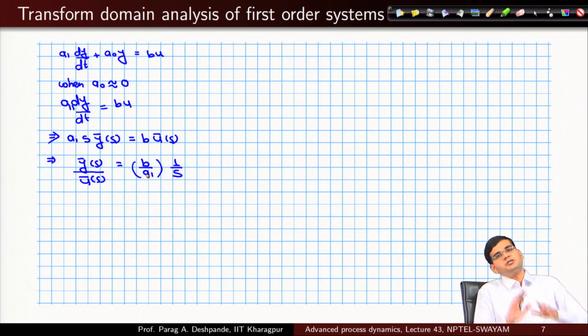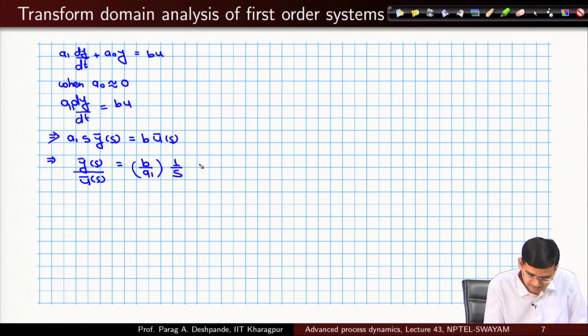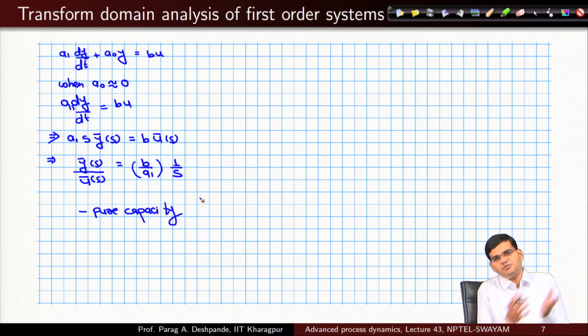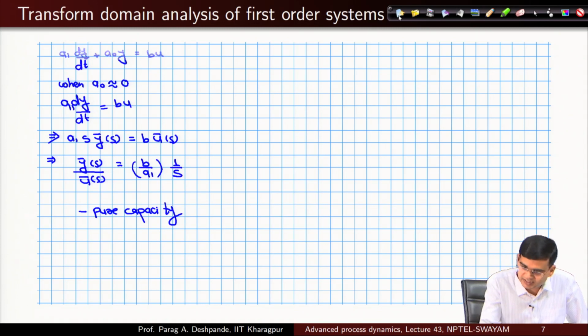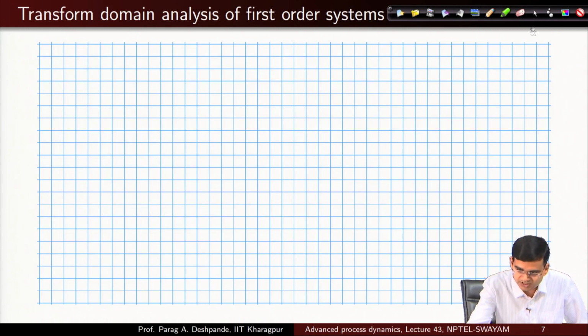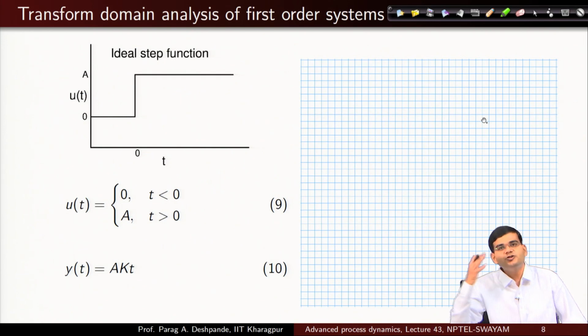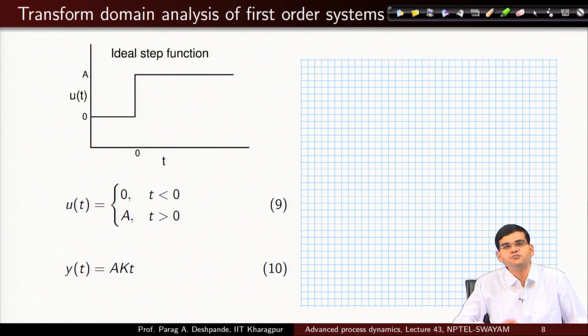Okay. So, this will be the functional form of your transfer function, and such systems are called pure capacity systems. Well, the solution method will remain the same. You will write the Laplace transform for the forcing function and take the inverse Laplace transformation, analyze the dynamics. But these particular systems offer very interesting dynamics, and when you come across such systems, you need to be really careful, because your intuitions regarding the usual responses will not work.